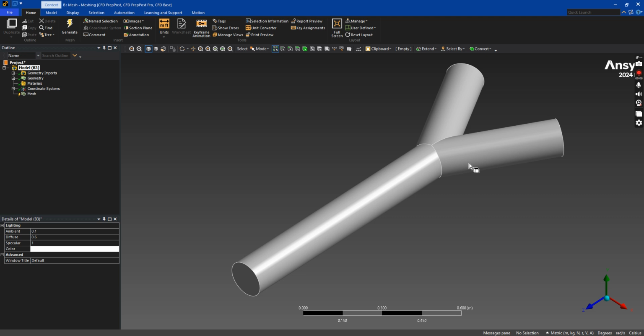While generating, the mesh can change its shapes rather than the geometry. So the patch conforming method ensures that the meshing does not change the shape of the actual geometry, not even a bit. So this is what the terms mean. So now we are moving onto the meshing.